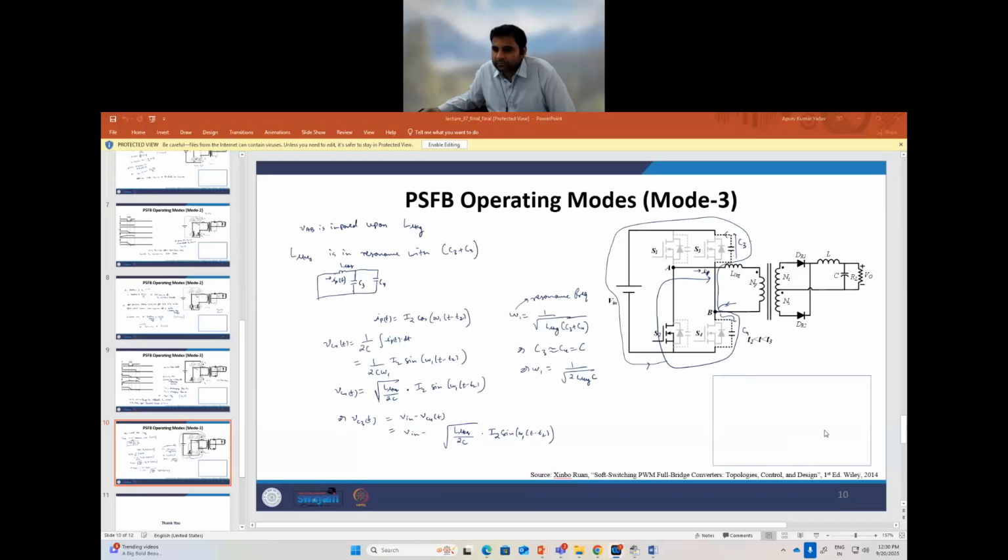What I'm trying to say is that the half bridge which is not switching for the entire half cycle, you make it operate as an active bridge. So both are active bridges, and then you can do the bidirectional functionality. A simplistic way is to make it operate as an H bridge, just like the case we did in the three-phase system. The same way you can consider this as well.